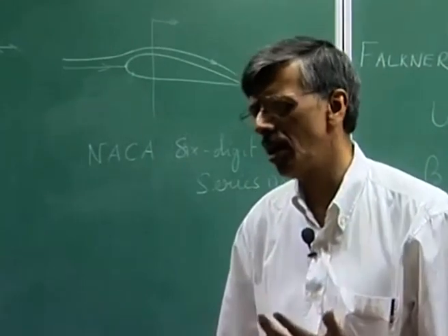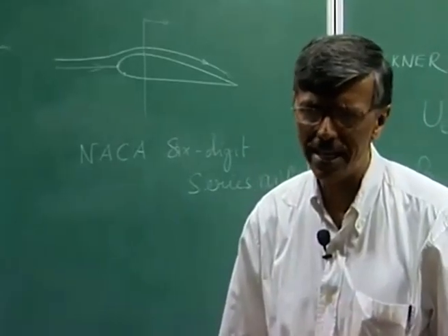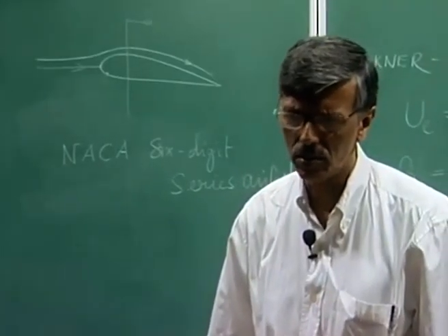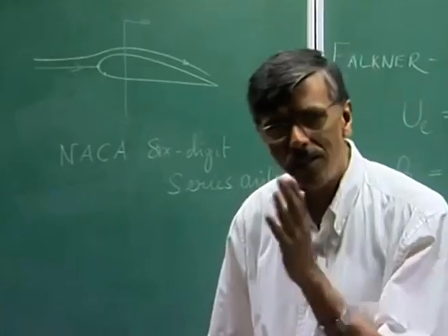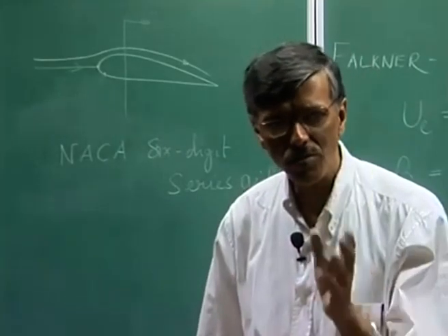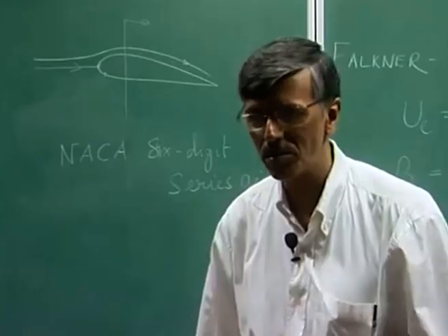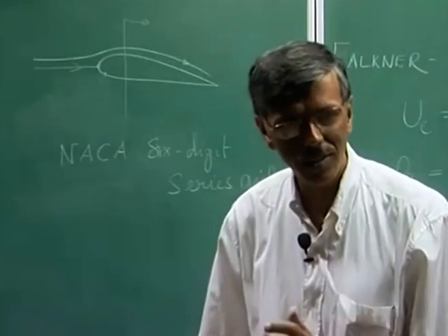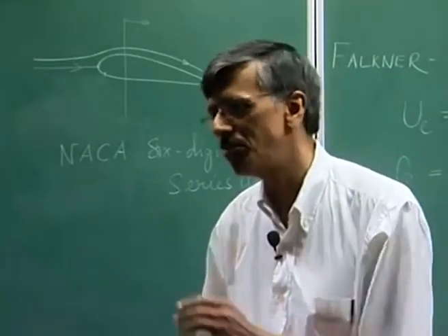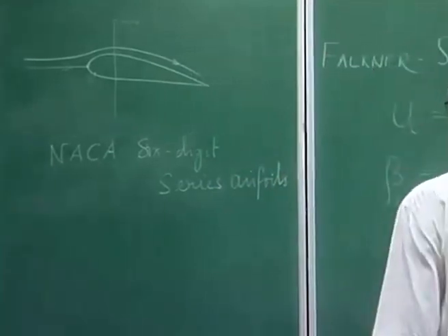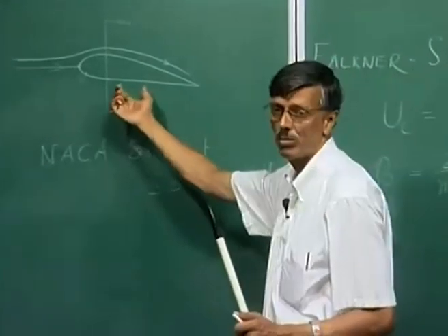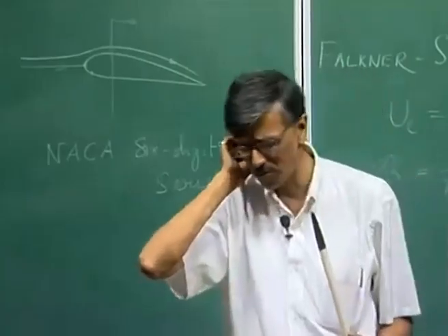That is what you should look at in any aerofoil data book, and you would notice how the maximum thickness and the position of maximum thickness point have changed during that period. These 6-digit series aerofoils try to push the maximum thickness point as far back as possible.